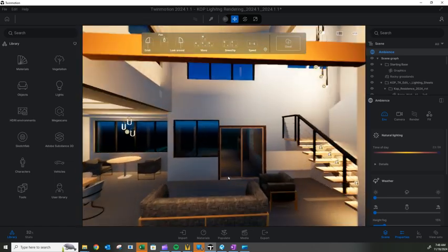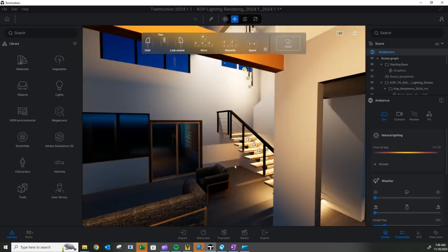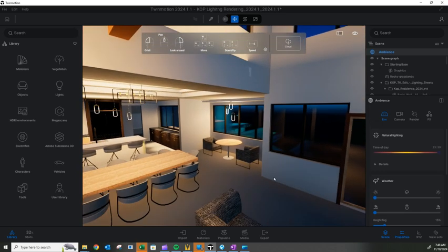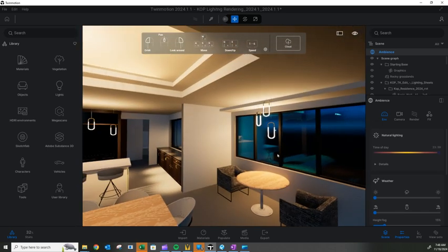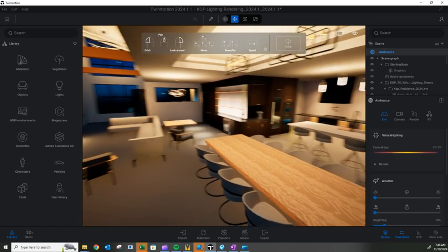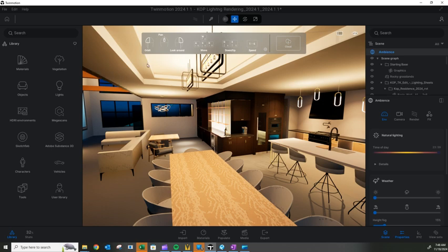And then you go over here towards the stairs. You can see stair tread lights. You also see the decorative suspended light, and then there's also some recessed downlights to fill in the space with ambient light. So that's a lot of what it is. That's the technique called layering. Over here we have downlight, single pendant or multi-mini pendant. In here it's a cove light, indirect up, and then there's also recessed downlight shooting down.